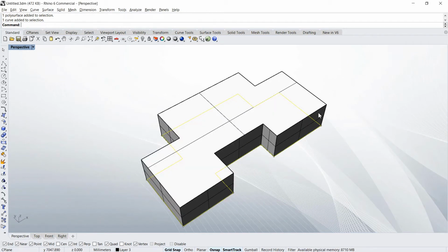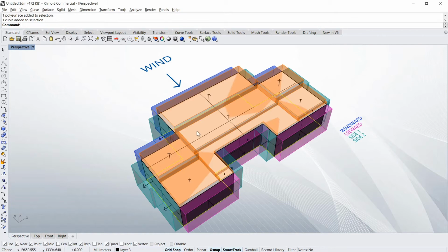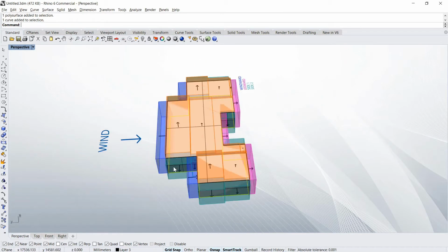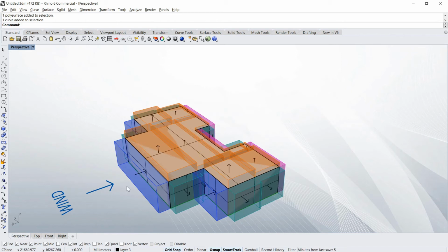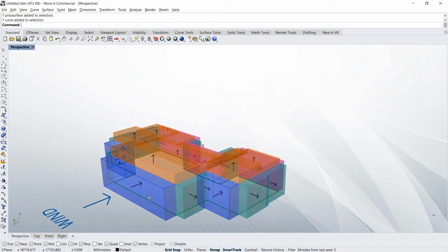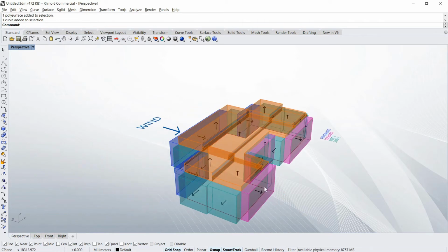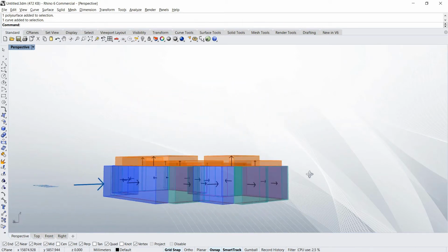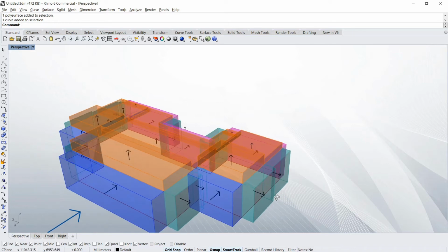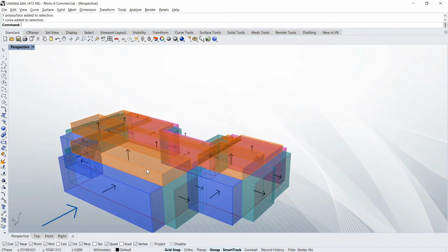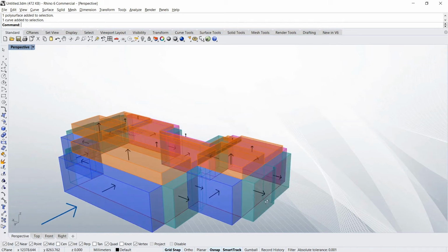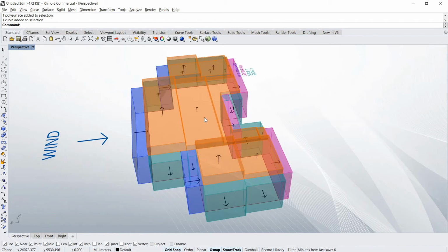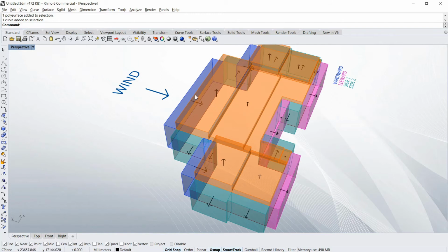And finally, you can see the effect on a larger and more complex building. If I apply a north load on there, north wind, you can see obviously again the biggest effect is on the front face, a less effect on the rear, and for the roof and the sides, the effect pulls away from the building or upwards away from the building, but it steps back as you get further from the leading edge of the wind.